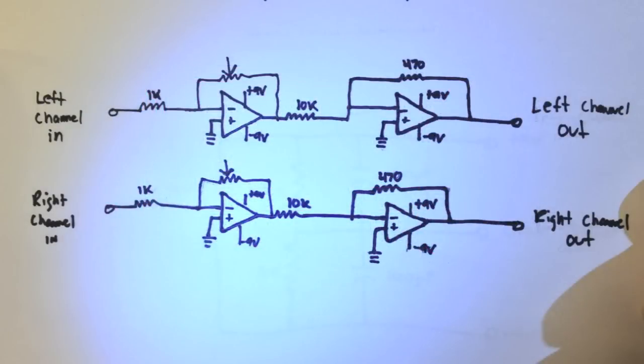This is the schematic for our audio amplifier. Essentially, it consists of 4 individual operational amplifiers with a supply voltage of plus and minus 9 volts on each of the amplifiers. The 2 resistors going across each amplifier control the gain of the circuit. These operational amplifiers are hooked up in inverting amplifier mode. The gain becomes the upper resistor divided by the input resistor.